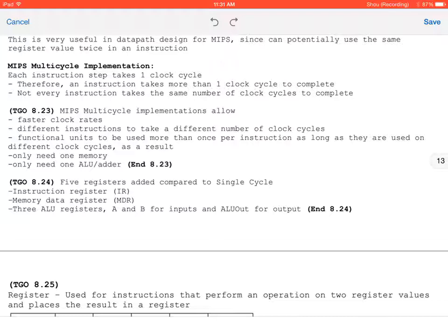And for those of you who haven't learned MIPS, there are 5 stages. Instruction fetch: get it out of the instruction memory. Instruction decode: we decode that 32-bit binary value into an opcode and register values, which we'll discuss in a minute, precisely how that's done. Execution goes to the arithmetic logic unit. It does some sort of actual operation.